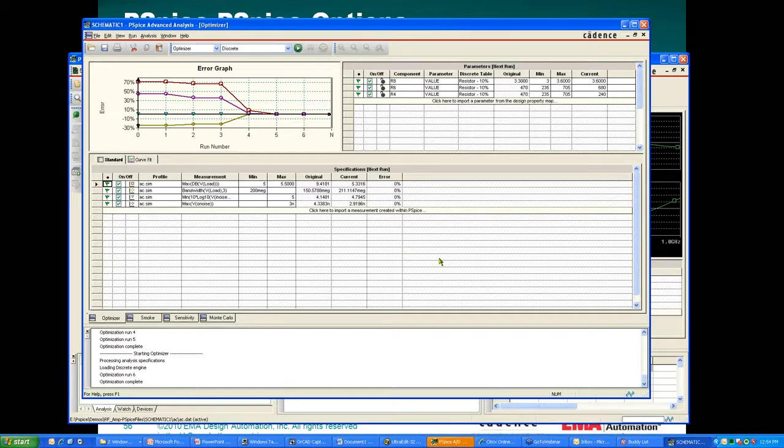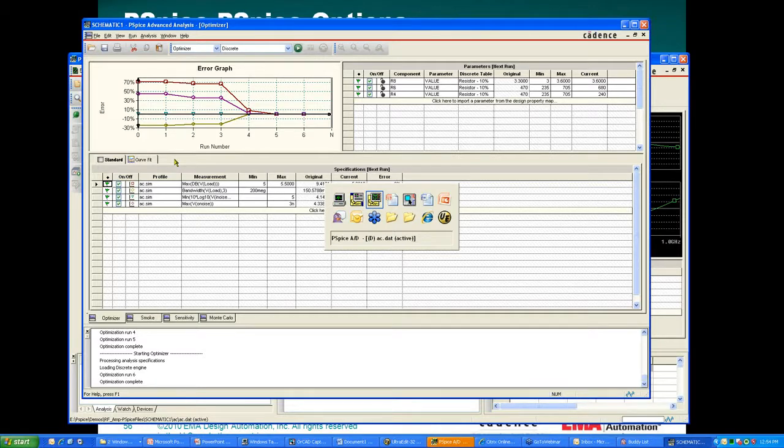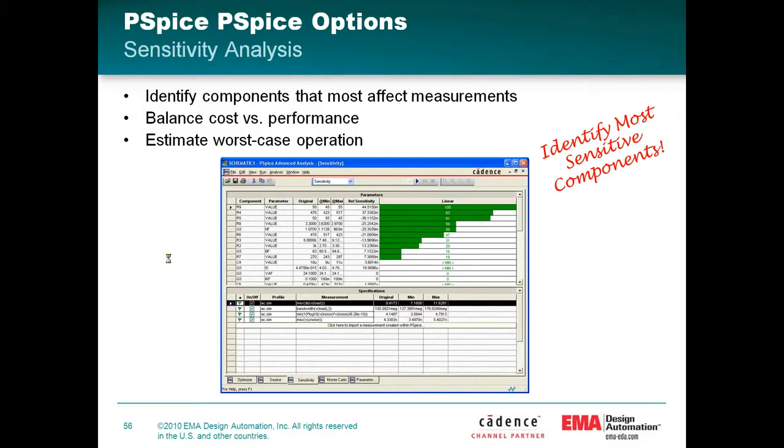Okay. You can also do curve fit. I'm not going to show you that today in the interest of time, but if you have a particular XY parameter set up that is a curve plot, and you want a particular characteristic to try its best to meet that curve, you can certainly do that as well. You basically apply that parameter, have it read that particular XY plot, and associate which column is which axis, and it will go and do its best to achieve that fit in the same manner. Okay, back to the slides.